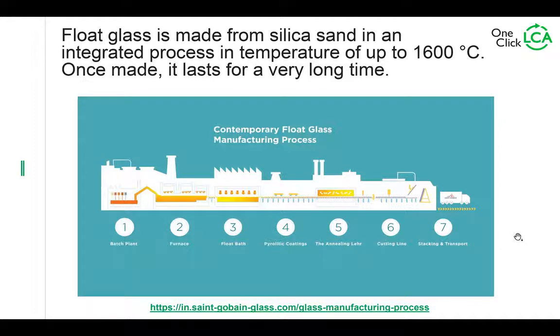Right. There's a very good comment about trying to increase building air tightness with spray insulation filling gaps, and what was stated about not using spray insulation. So sure, improving air tightness is a good application. So then you would just control it, but it wouldn't be used in significant quantities in such a case. But then you would need to know what blowing agent is used.